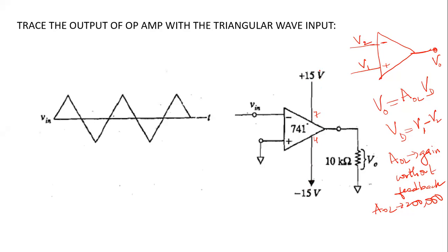It consists of, I think, around 22 transistors. In order to operate those transistors, you need to forward bias the emitter-base junction and reverse bias the collector-base junction. For turning on the transistors, you are supplying this DC signal, plus 15 and minus 15 volt. Depending on the resistor connections and all those things, it gives the proper biasing to the transistors within the op-amp.